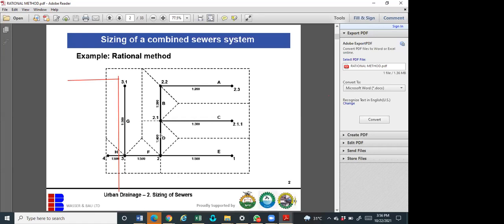You know that, look, as the tributaries are coming in, the flow is increasing. Gentlemen, this is common sense. But it's so difficult for a lot of people. That's why when you see some designs people do, they will use uniform pipe sizes. And you begin to wonder, does it mean that this flow is not increasing as it's going downstream? If it's water reticulation, as the pipe is getting towards the elevated tank, it's getting bigger.